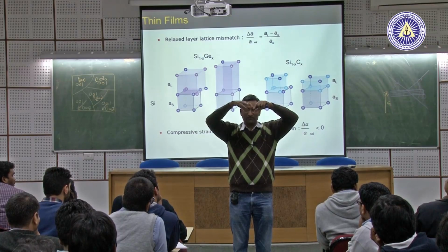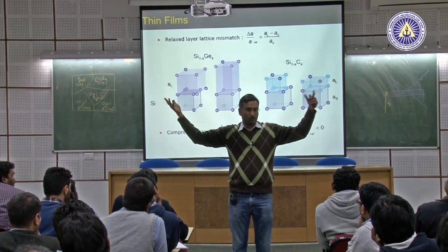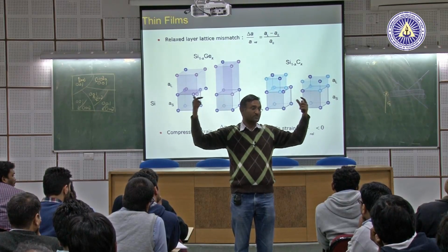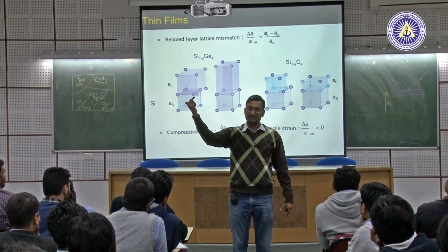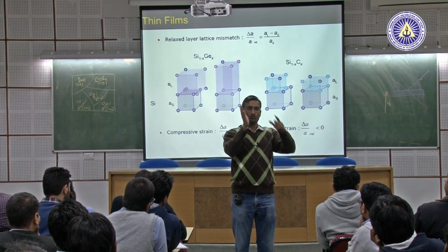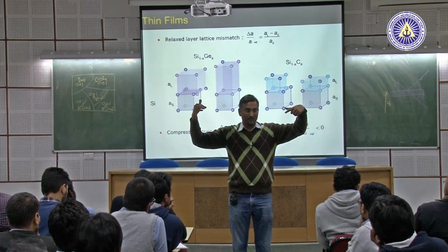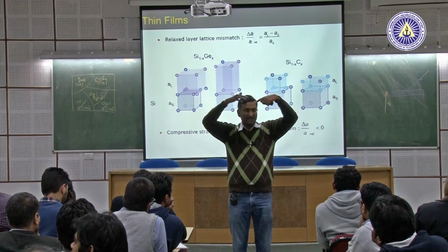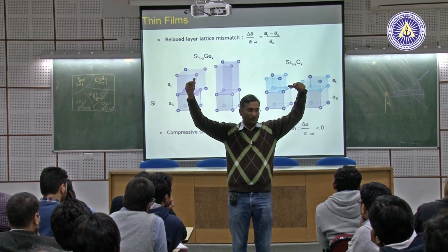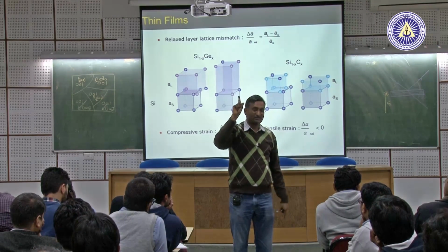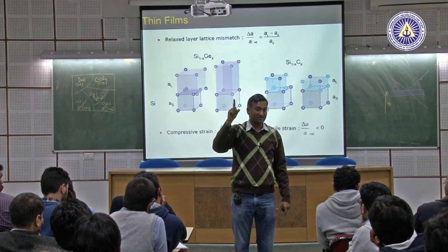So, the thin film will be strained in either tensile or compressive fashion, but if the strain is too large, then let us say you want to match 10 angstrom by 10 angstrom: you will have 10 atoms at the bottom and 11 atoms on the top. What will it mean? That one atom is free, and this free atom will mean a dislocation.